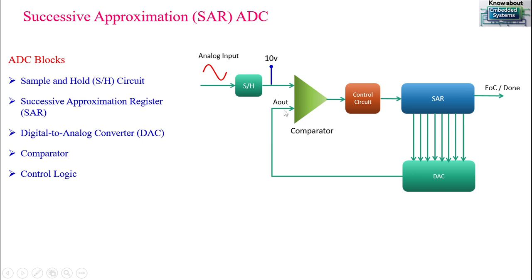Okay, so one input, our DAC output, is given to the comparator, and one more input to the comparator is your sampled input. So what happens here is, whenever the DAC voltage is falling, before that you should understand how the SAR will work. SAR will keep the MSB as 1. This I'll explain better in the next slide.